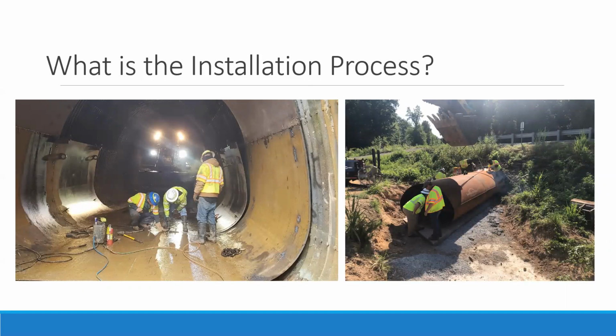I want to mention here that each liner section is shipped in an 8 to 10 foot length, and the ends can be beveled to allow for welding on the inside or the outside of the liner. And full penetration welds eliminate the possibility of joint failure.